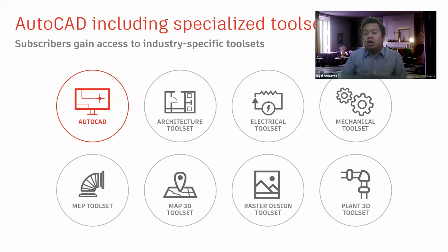Okay. Is it possible to get working drawings from JPEGs or PDFs into AutoCAD? So that's a bit of a loaded question. It is possible to get working drawings from PDF files if the PDF is a vector-based PDF. So AutoCAD added some functionality a couple of years ago with some of the PDF import tools to be able to bring some of those files into AutoCAD and start using some of the lines and text if it can determine if it's SHX text or not.